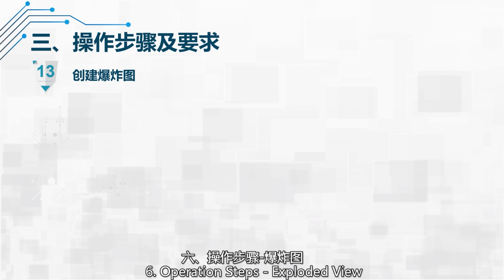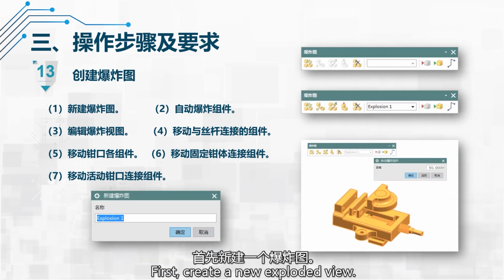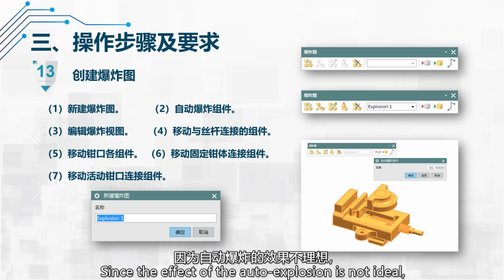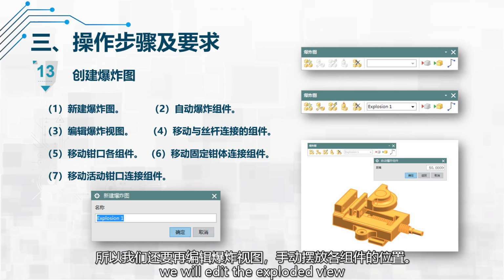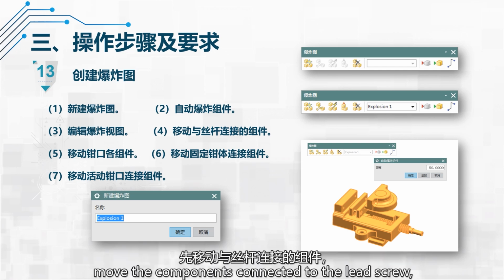6. Operation steps. Exploded view. Next, we will create the exploded view of the bench Vise. First, create a new exploded view. Then click Auto Exploded Components to perform an initial explosion. Since the effect of the auto explosion is not ideal, we will edit the exploded view and manually position each component. First, move the components connected to the lead screw.